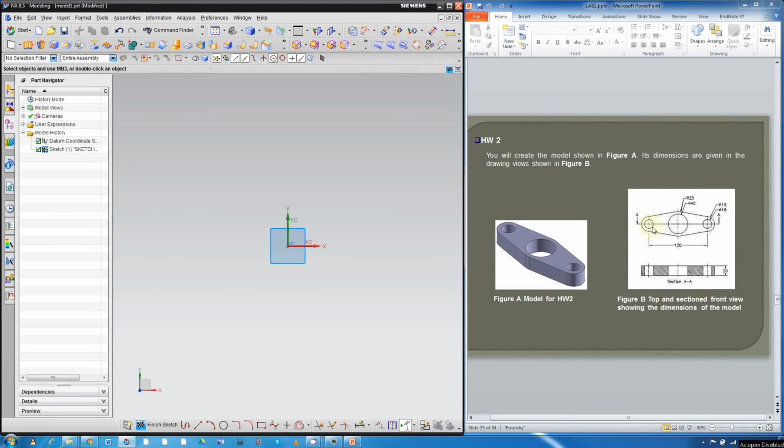Alright, let's look at the shape. Although this is symmetric, there's a circle cut in half by the center line, so that will take some time to draw half of the circle. So I'll just draw everything at once. And you have two circles, equal and at the same distance from the center. Remember we talked about the reference line in part 1 of the lab. So we can have a reference line here, then put two circles onto the reference line.